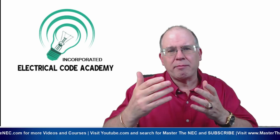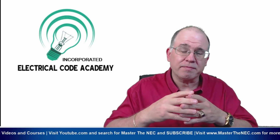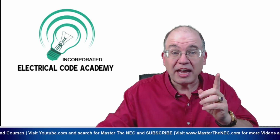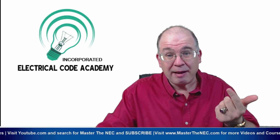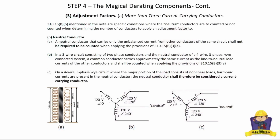And since it carries the imbalance of the load, it doesn't have to be considered as a current carrying conductor. However, that is not always the case. That's just an example of where that might come into play, and you don't have to count the neutral. All right. But there are 2 applications where that is not the case. And here's the first one.